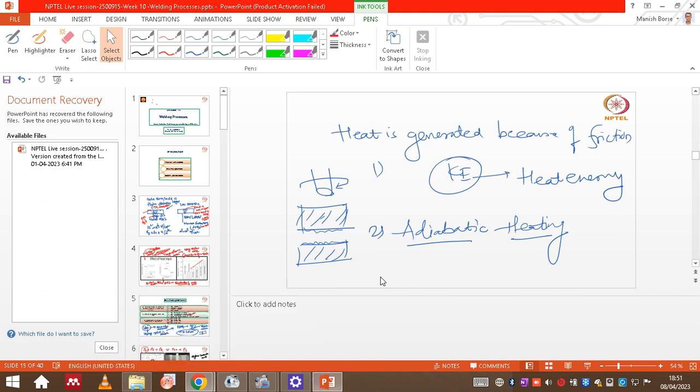No, actually, it won't form any microporosity, but it will form certain defects. Let's say we don't maintain proper edge preparation. Let's say we cut the interfaces to be joined with, say, a hacksaw or something, not with precise machining processes.